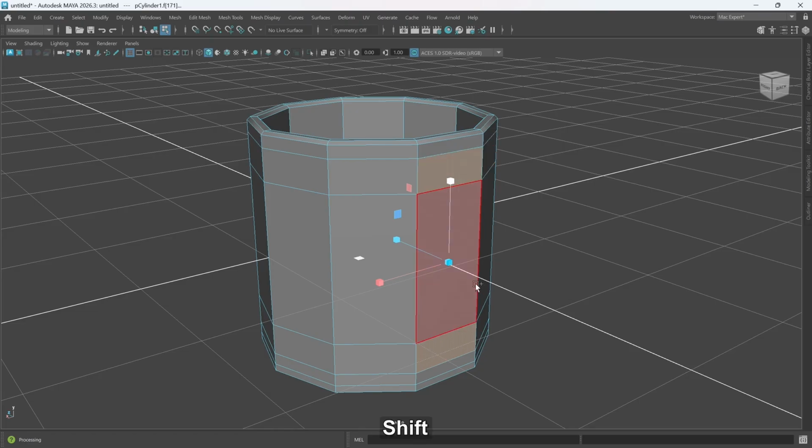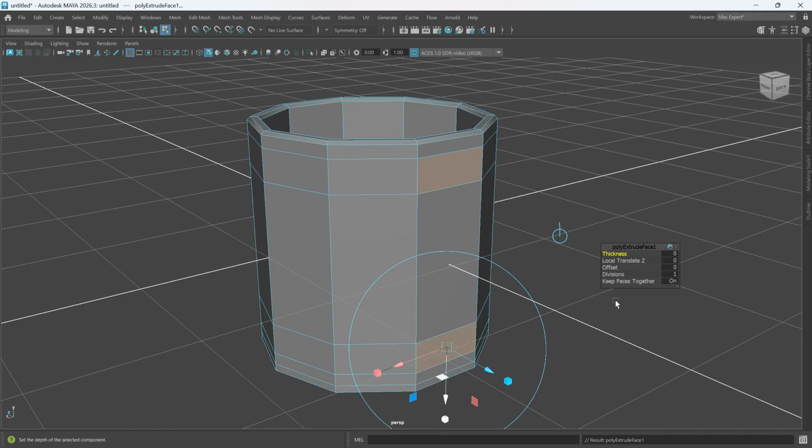And I know at this point you want to make use of this method to offset the face. Of course, you can see what is going on here. So that technique of the smart extrude has its own limits. You don't want to use it here. So at this point, you just go and hit Control E to extrude and go to the offset and offset inward just like this.